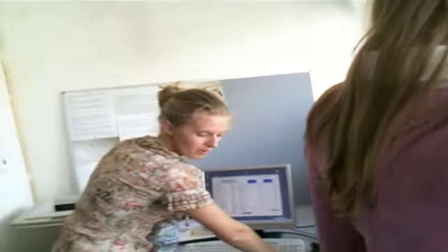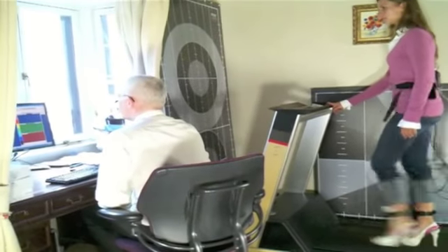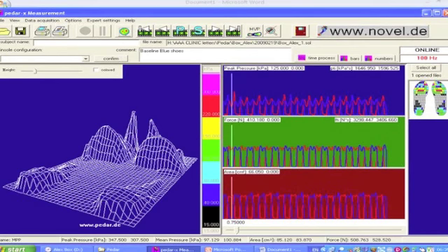You start with a 3D foot scan to take the contours of the foot, because everyone has different shaped feet. You then put on these 5-inch heels, as you can see here, and then you walk on a treadmill, and at several times a second we can scan the pressure distribution exerted on the inside of the shoe. What we then want to do is create variable cushioning, like you saw with the variable density of the bone, to counteract exactly those loads.